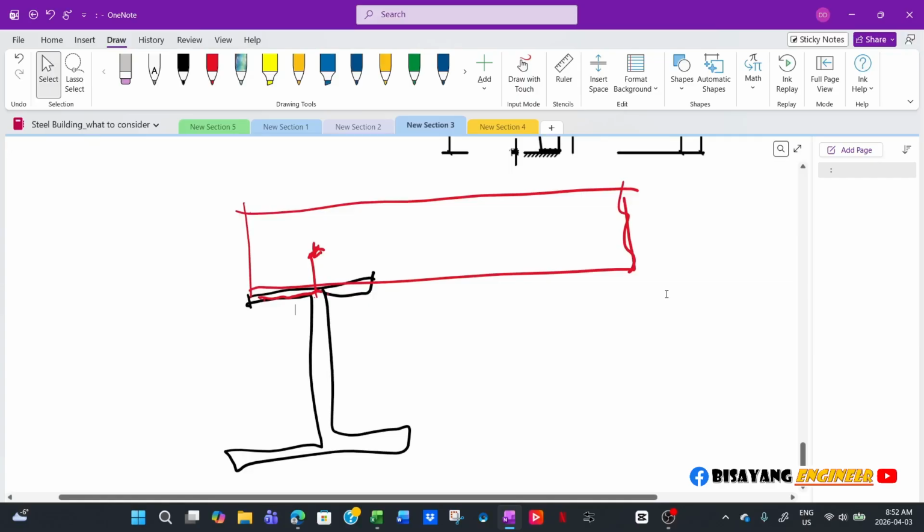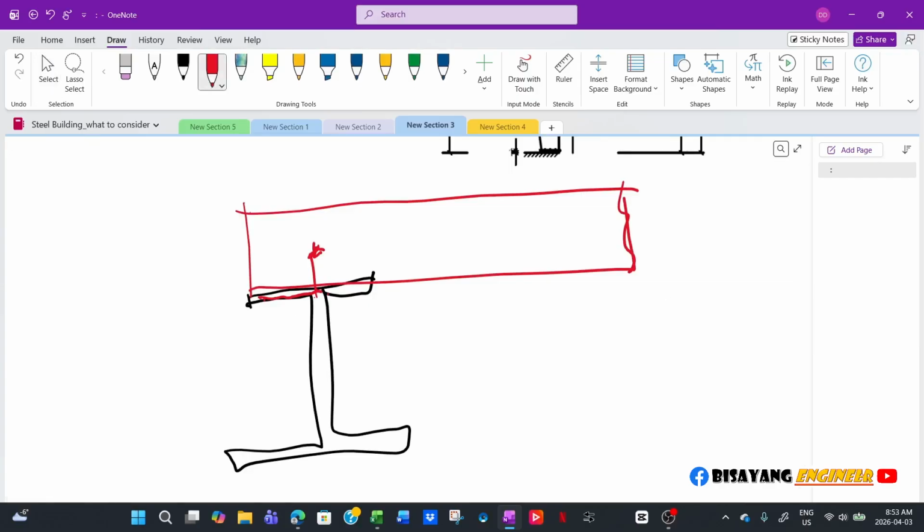Now, if you look at this closely, your force basically starts from the joint here, I mean, transfers from the wall to the frame, and then it transfers here. So this force at the joint, this intersection here, will create a compression and at the same time negative bending of the purlins. So the purlins will bend upward, right?